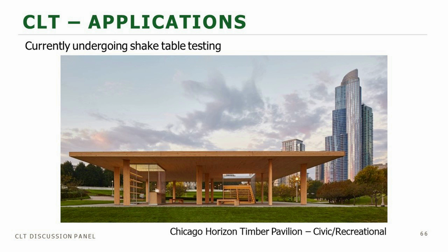They're typically not going to be carrying the load in two directions. They're uniaxial members, so they have one major axis that carries the strength in that direction. CLT is a panel product, so it carries the load in two directions, and that allows us to develop what's called a major and a minor axis. So it does eliminate the need for things like interior beams or interior supports.